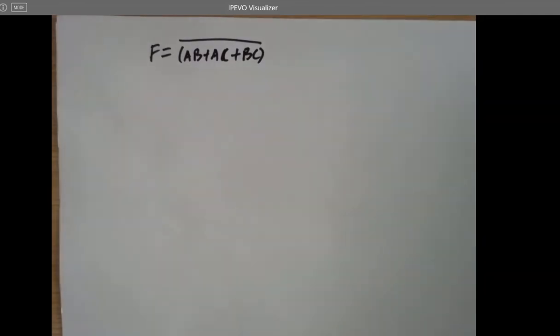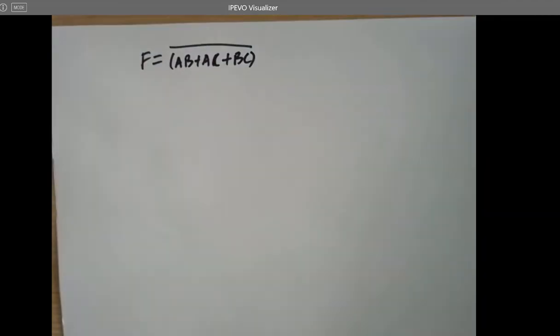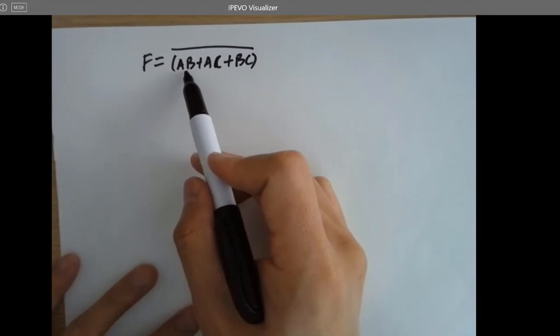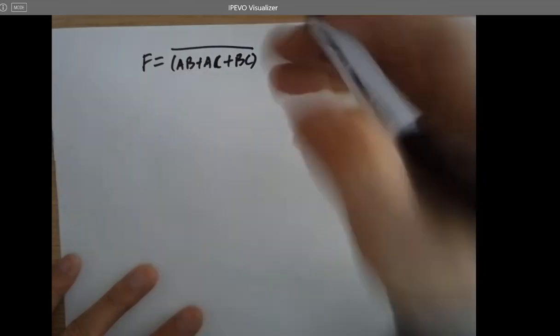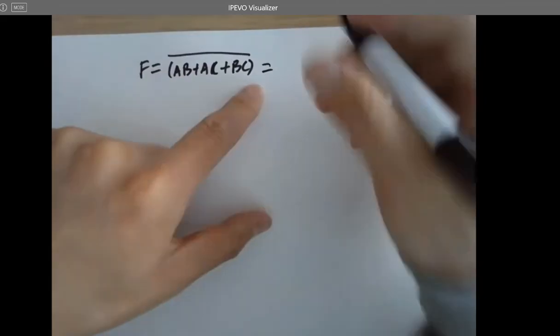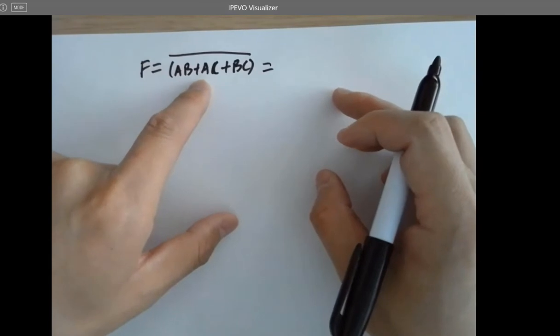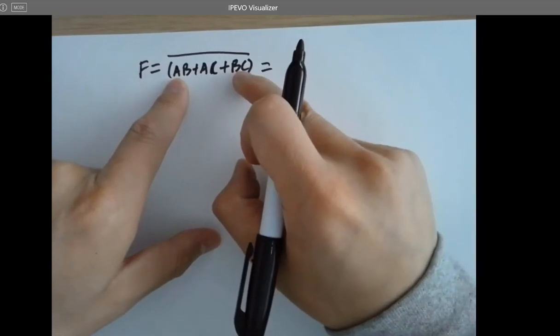Yes, since you have a bar on top, right? Start doing this. AB is the AND logic. So for the PMOS, they should be in parallel, right? AB. So what I did over here is, you can do it either way. You can directly have 3 components in series on the top of the PMOS.